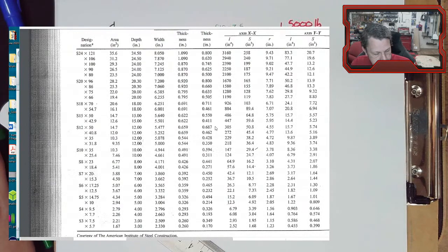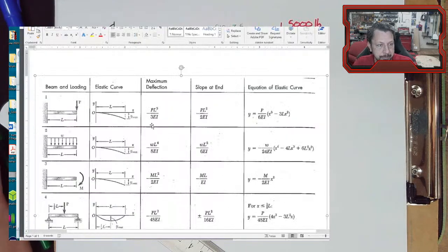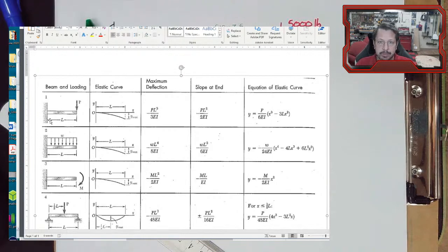All right. So I think that gives us enough to get started with our beam chart. Let's say that we just want to know the maximum deflection. So let's go through what we have on this chart. We've got a diagram showing the loading. You do have to match this exactly. Sometimes you have to mentally mirror image things or whatever to make them match your case.